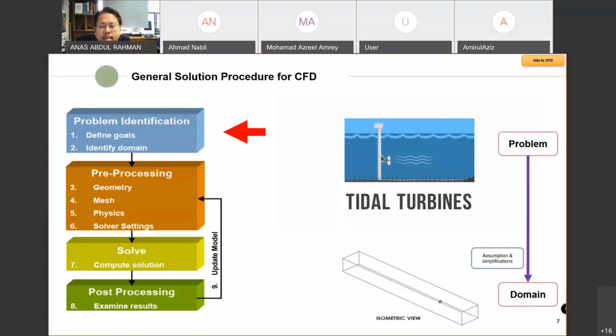If you are just interested in the flow interaction, the vortex mixing, or what we call the wake, basically, if this is the inlet from the left and this is the outlet from the right, you're just interested in the wake formation, meaning that you have an inflow and then a deceleration because you have an object, and you want to see how long the flow needs to go downstream to recover the initial velocity of the inflow.